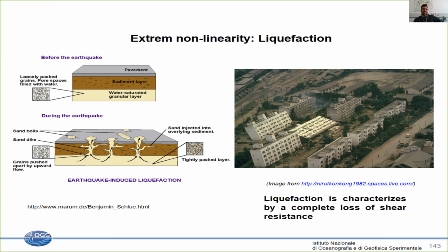In that case, the pore pressure was increasing because the saturated soil material that liquefied was just below, for example, a frozen layer of material. And below this frozen layer, the pore pressure is not able to dissipate anymore. So you have a large increase here and then it's liquefying. And in this way, we also explained some earthquakes in Central Asia that happened more than 100 years ago.